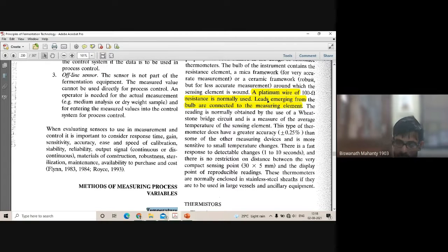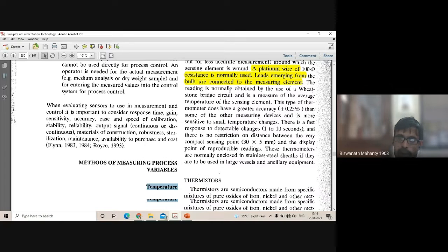There are so many moving things, and glass is fragile. So a glass thermometer is only used in very small scale without much agitation. Otherwise, for most measurements we can use a thermocouple. They are really very accurate, particularly in an industrial process. So we will be talking about those.